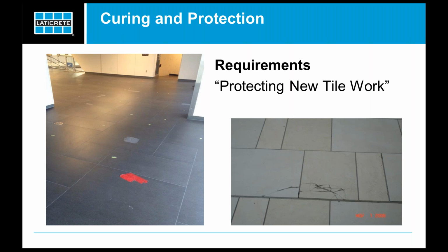And then again, protection. We talked a little bit about it a few minutes ago, but this illustrates what happens when these floors aren't protected. You can drop things on them. You don't have good coverage. Edges chip. This is one of the most disturbing things I ever see when I see installations, is to see edges cracked like this. It really is unsightly and takes away from our industry as a whole as to the durability of tile finishes.